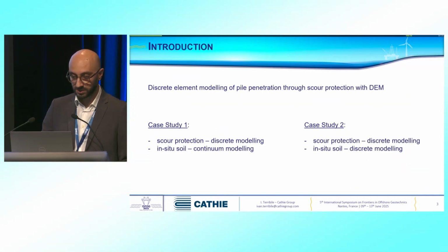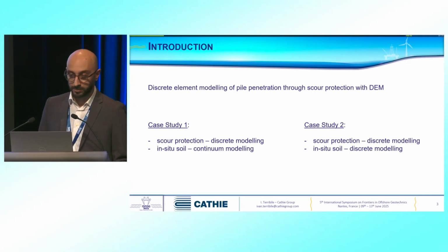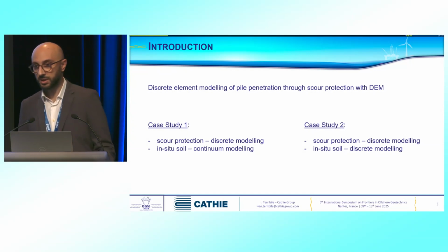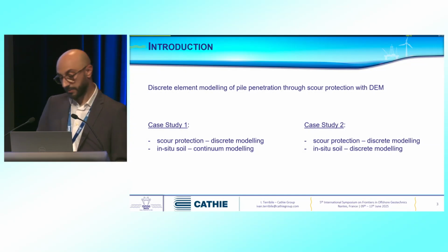So in this context, I will present you two numerical studies where the penetration of the monopiles was modeled with the discrete element method. Regarding case study 1, only the scour protection was modeled with the DEM, while the in-situ soil was modeled with a continuum approach. In case study 2, both the scour protection and the in-situ soil were modeled with the DEM.